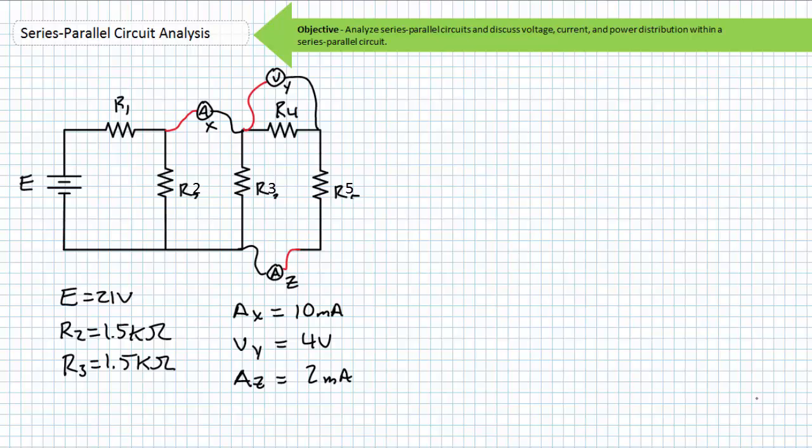However, it requires absolutely no additional skills besides visualizing the circuit at the nodal level and from the perspective of flowing current. Current in a single path is the same. Voltage across paths in parallel is the same. For every rise there is a drop, and what goes in must come out. Given the following components and instruments and their observed values, solve for the voltage drop across all components. Solve for the current through all components, and solve for all unknown resistances.